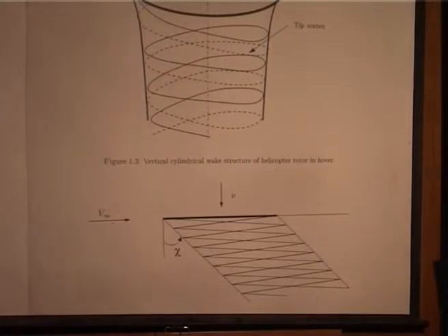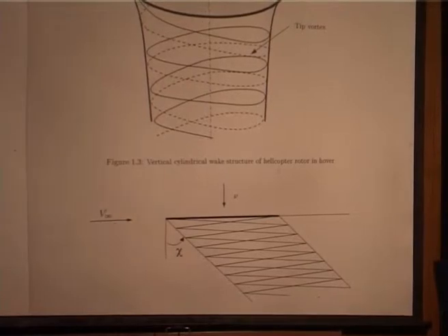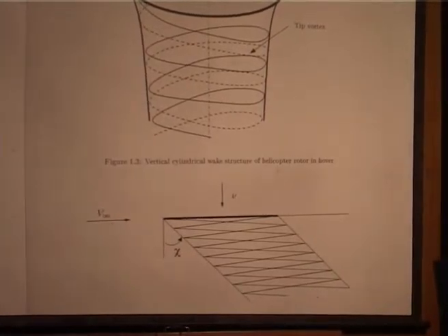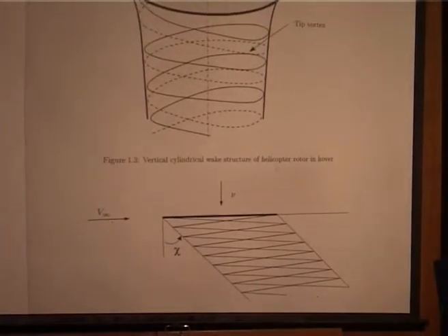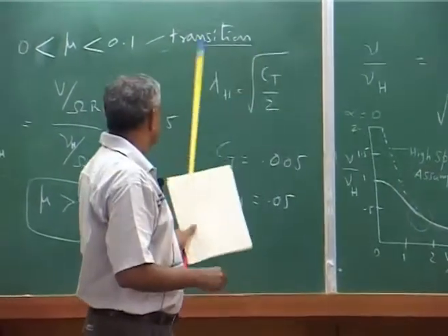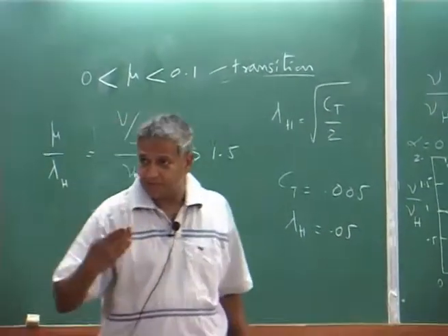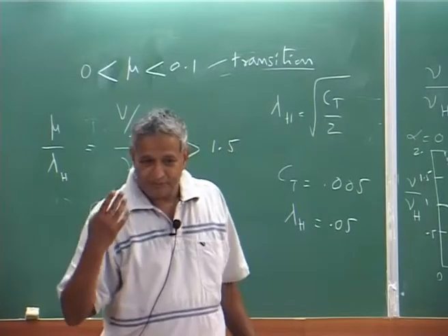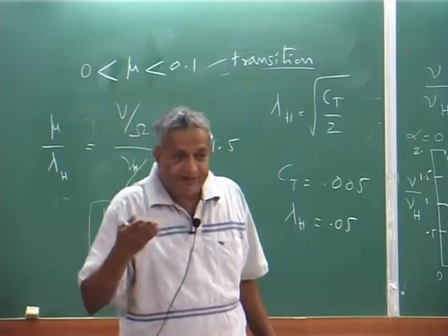And this really complicates the problem, because the wake is close. When the blade travels, the wake from the front blade will come close to the rear blade. Usually you will have high vibration, etc. in that transition zone. Normally helicopters you don't fly in this. Of course, when you increase the speed you will be going through that, but you don't try to operate fully flying there.